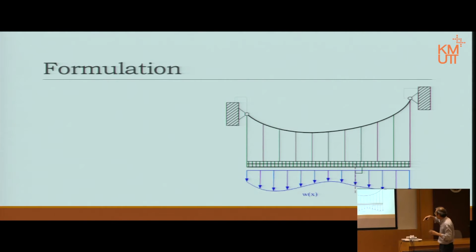Now the load, of course, comes from the self weight of the bridge. That load can come from the beam, from the slab, from the pavement, and of course from the traffic on the bridge. The traffic goes into the pavement, into the road. Then the weight of the road and the weight of traffic transfer to the beam. Rather than all of it going through the beam to the column, most of it will actually go to the cable suspenders and then hang up to the main cable.